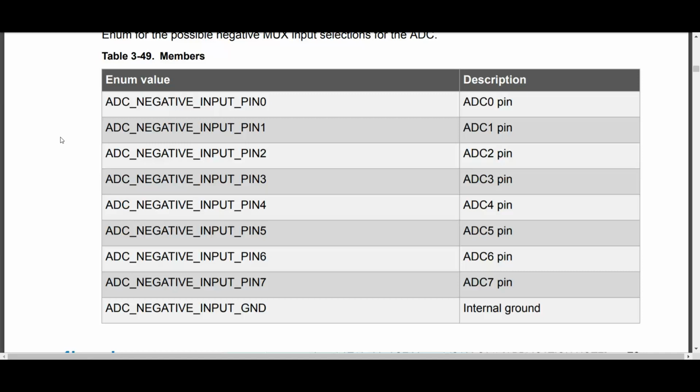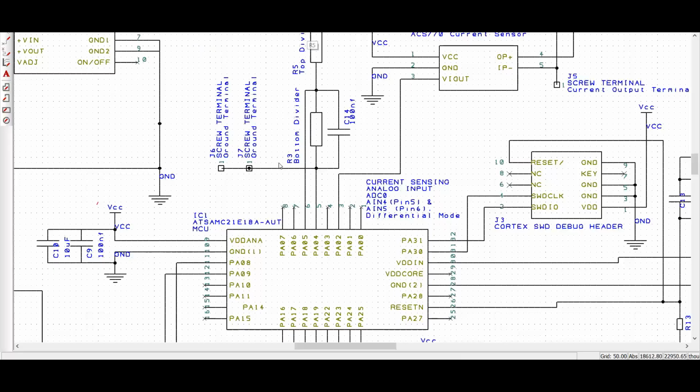Now, my other choice is to wire the bottom of the resistor network here to actual physical ground of my board, but I've wanted to avoid that because that means the ground of the motorbike's drive system is going to be the ground of this board, which means the ground of this board goes back up to be the ground of, say, the laptop you've got plugged in, that's configuring potential settings while the system's powered up. And that gives me the willies.